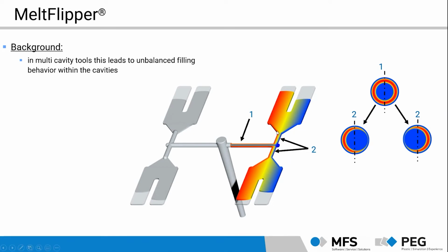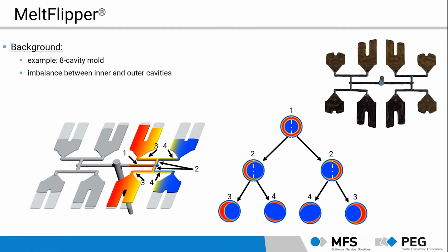You have the higher sheared material on the inside here, so this flows into the inner area of the cavity, and we have the lower sheared material, so the colder, slower flowing material, here on the outside of the cavity. So we have different temperatures. We have a temperature distribution which is not equal over our cavity. And we have also a different filling speed.